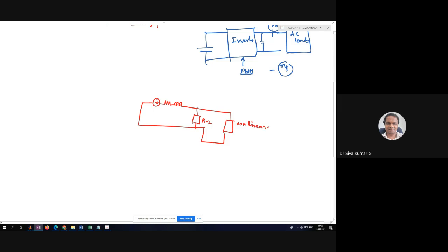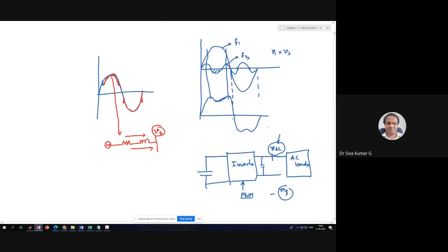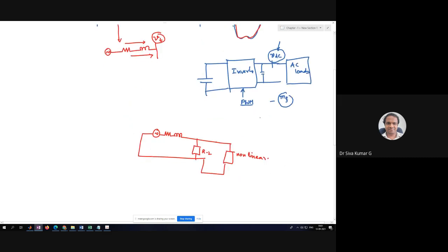You know that if you allow these kinds of currents, especially those having the third harmonic current, in a system, obviously at this particular point at the terminal, if you say this is Vs and this is Vt, you will be seeing that Vt is equal to Vs minus Is, especially the nonlinear load current, into Zs.